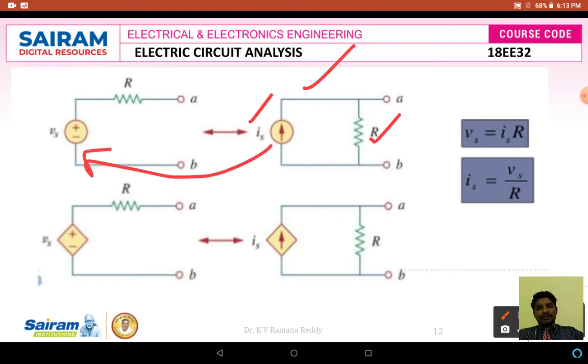What is the formula from Ohm's law? We know the formula from Ohm's law: Vs is equal to Is into R. Here we already know the value of Is, and we already know the internal resistance of this Is, which is R. By multiplying this Is and the internal resistance of this current source, we can calculate this Vs.